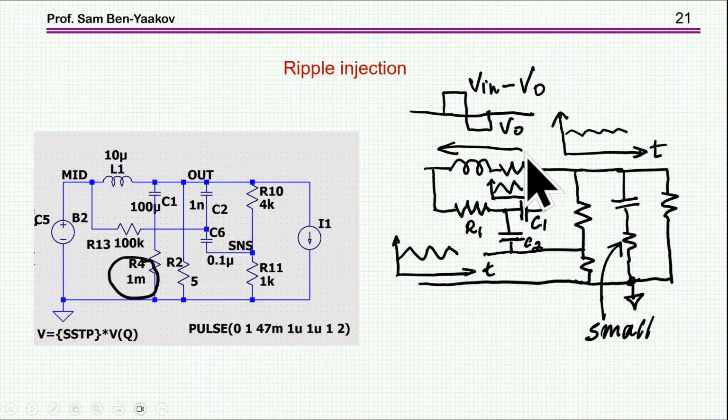Not only that, it is more like a ripple of a capacitor. It's not reflecting the resistance anymore, and therefore there is a phase shift. So in fact you cannot use it for this operation because it's not in phase with the switching cycle.